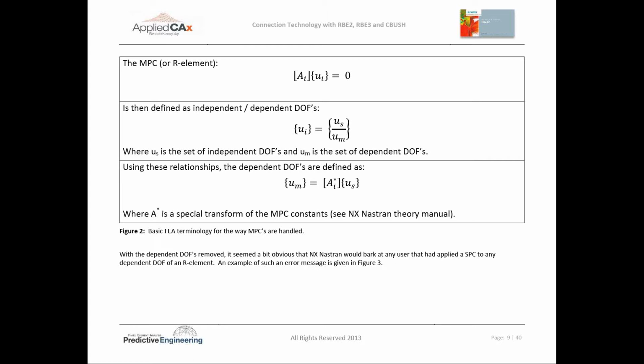It will also tell you it's a linear element. If you do a geometrically nonlinear analysis, it has no idea what is going on with a rigid link. Anybody that uses LS-DYNA knows rigid links don't exist. They call it a coupled nodal rigid body. You take a group of nodes, couple them, and turn them into a rigid body so it can spin and move. If you use solution 601, again, rigid links don't exist.